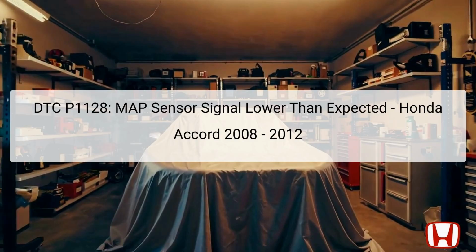The sensor is located typically near the intake manifold, where it can accurately measure pressure variations. When the MAP signal is lower than expected, it may indicate that there is a blockage, a poor electrical connection, or even a faulty MAP sensor itself. Understanding the components involved and their functions is crucial for effective troubleshooting.